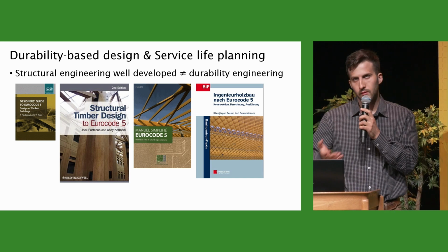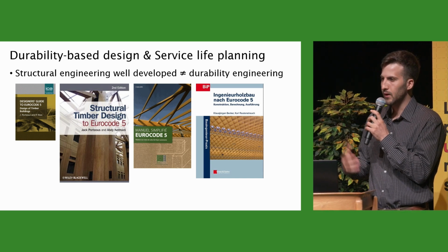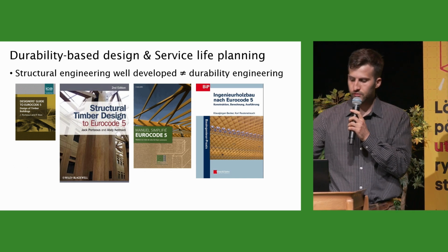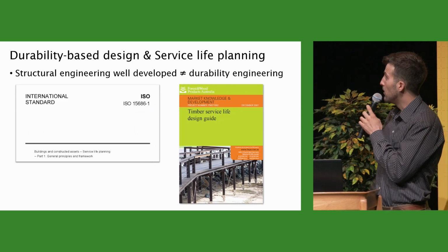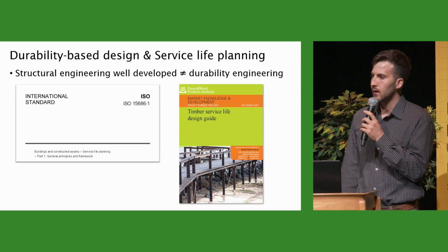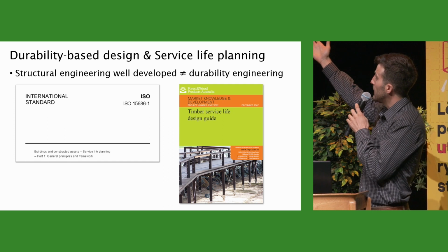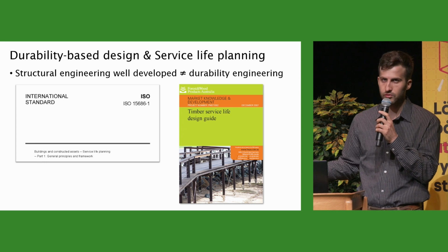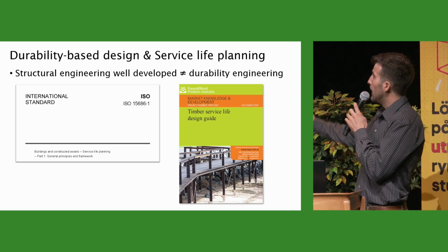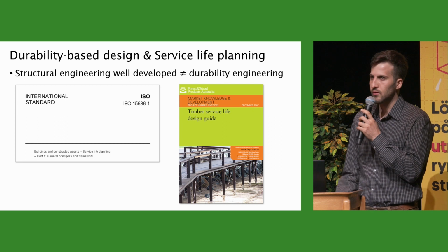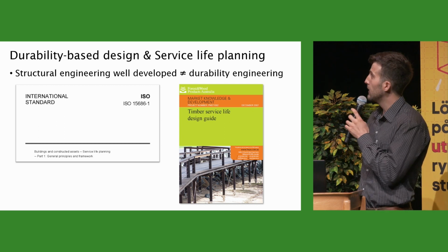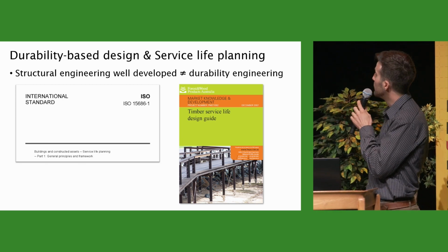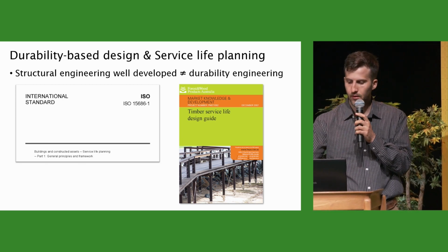So we know, and most of you in the crowd are familiar with, structural engineering design guides. However, there are not so many in terms of durability design. So we obviously have this ISO standard 15686, which is a general one for all sorts of materials. And then there's a few scattered guides on timber exclusively, and this is an example of one of them, the Australian Timber Service Life Guide.